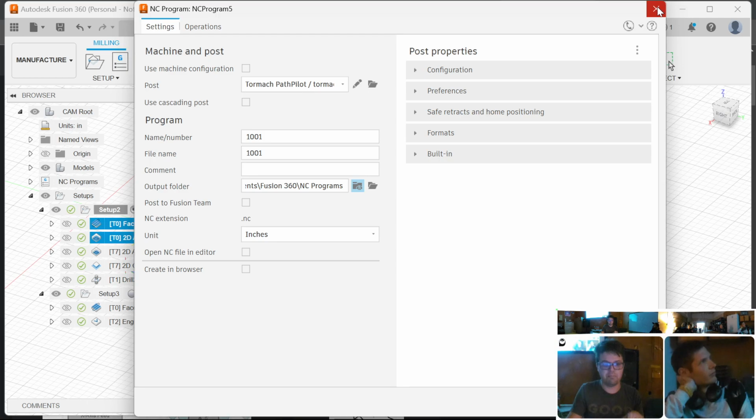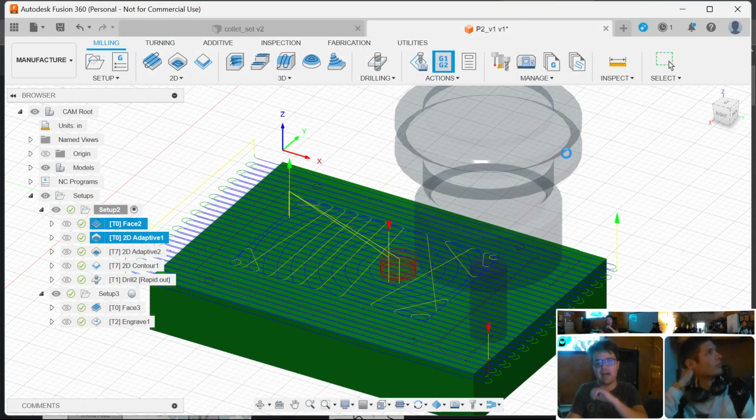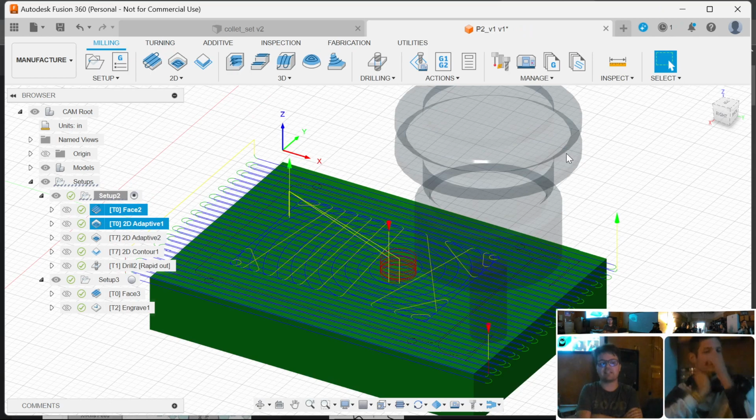Other things to mention in parting while we're still here. It is fairly easy with Fusion 360 to generate like 20 gigabyte G-code files. It will do things as precisely as you tell it to and generate absolutely ludicrous files. The files get fully loaded into RAM on both of the CNC machines we use. So if your file's over about 4 gigabytes, you're out of luck.